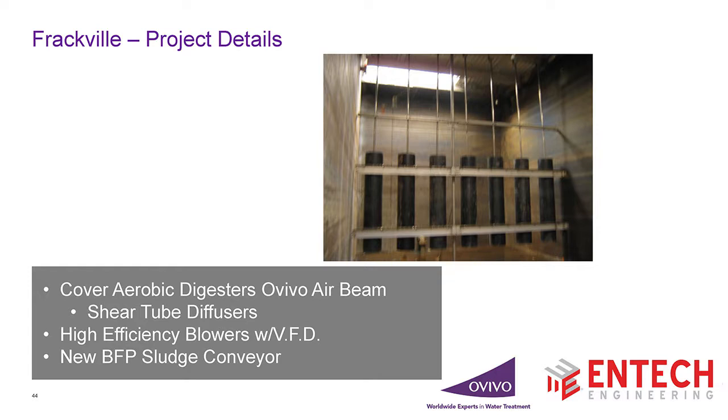But by sending the draft tube down to the bottom, we're pulling the sludge off the bottom. So we're getting the thorough mixing all the way down to the bottom, and we're pulling this sludge at high velocity past the diffuser, and that's causing the bubbles to shear and be more of a medium bubble size, if you will. So that's the diffuser setup in here.